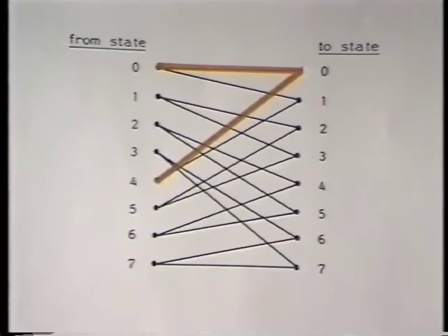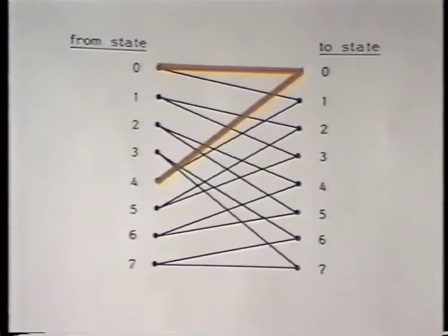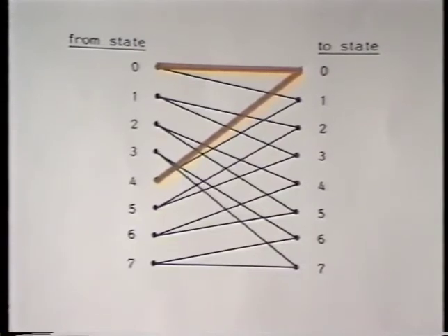Since after phase merger the worst of the two paths will never win, this can be eliminated, and thereby the number of states is kept to a limited number. In this figure, we have 8 states corresponding to a pulse duration of 4 symbol intervals. There are in total 16 possible paths in this figure.